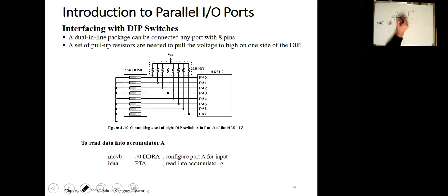You will read some value, but you cannot tell, because this pin is floating. So the problem here is that this switch can define only one state. It can connect you to +5 volt, or it can connect you to nothing.